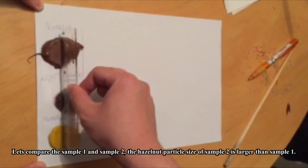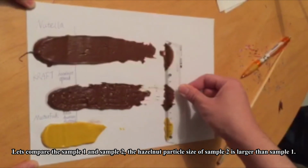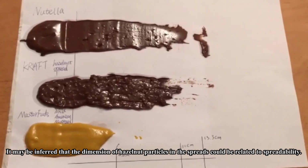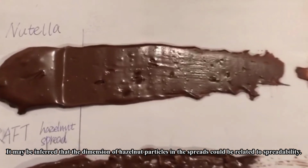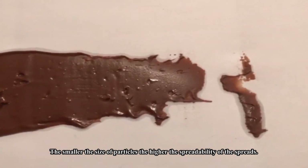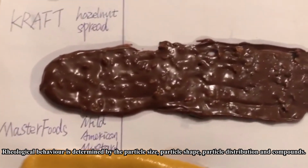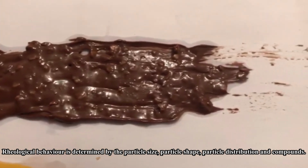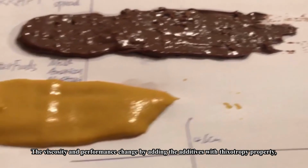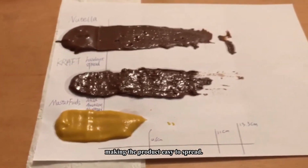Let's compare sample 1 and sample 2. The hazelnut particle size of sample 2 is larger than sample 1. It may be inferred that the dimension of hazelnut particles in the spread could be related to the spreadability. The smaller the size of the particles, the higher the spreadability of the spreads. Rheological behavior is determined by the particle size, particle shape, particle distribution, and compounds. The viscosity and performance change by adding additives with thixotropic properties, making the product easy to spread.